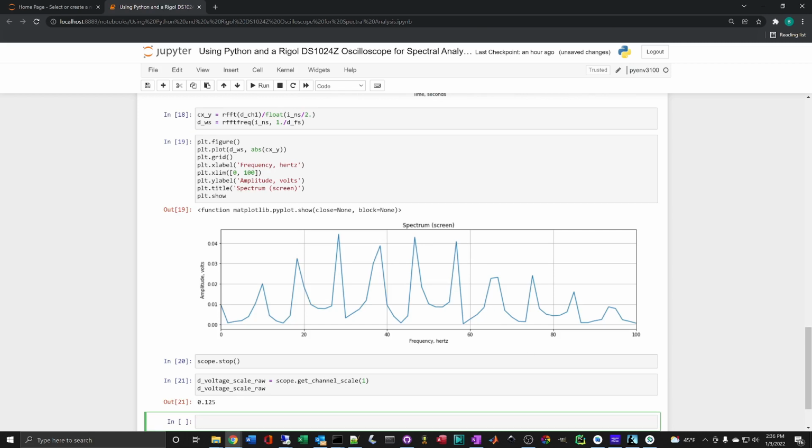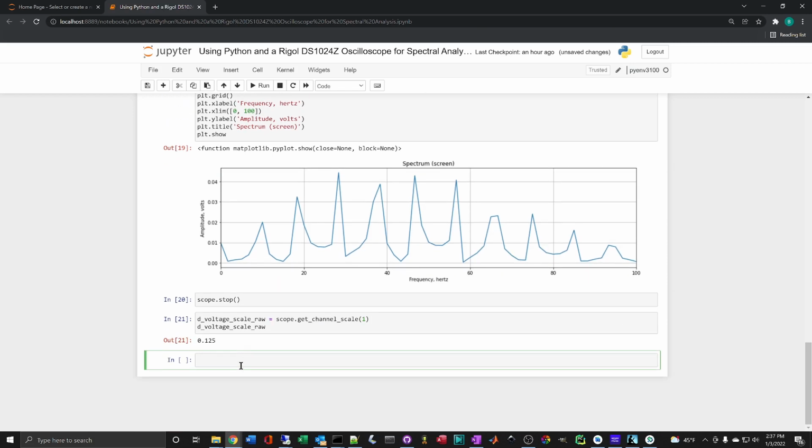So before we calculated the number of samples after we'd acquired the signal, and we did that because we knew we were always going to get 1200, so it's just an easier way to do it than entering it manually. But here we're going to actually acquire the number of samples and sampling frequency directly from the scope itself. So beginning with the sampling frequency, we're going to get that with a VISA query.